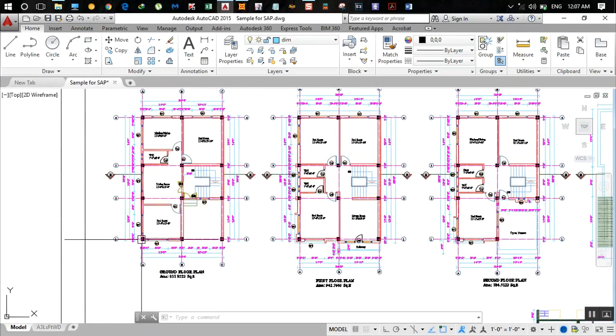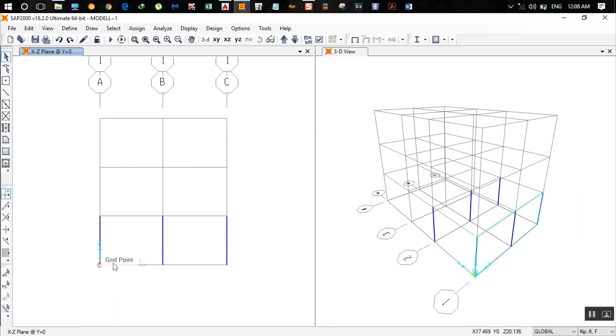So y is equal to 0 is at this place, right? So you are here now, and you have to move one step further into this grid. Alright, so for that click on this up in the list icon. So now we are in this grid. So up in the list doesn't mean up in the Z level only, right? Up in the elevation only. So its meaning varies according to the plane you have selected. Okay, so now we are here.